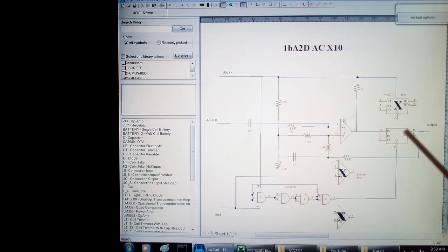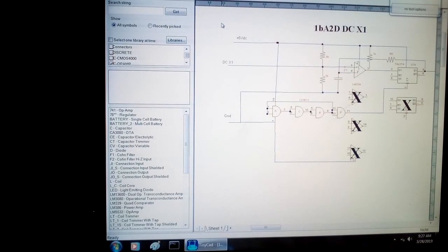Same arrangement with the flip-flop and the oscillator. I made the oscillator out of TTL this time, and it's significantly faster. It goes almost 10 megahertz. The time constant of the reconstruction circuit is about 5 microseconds.